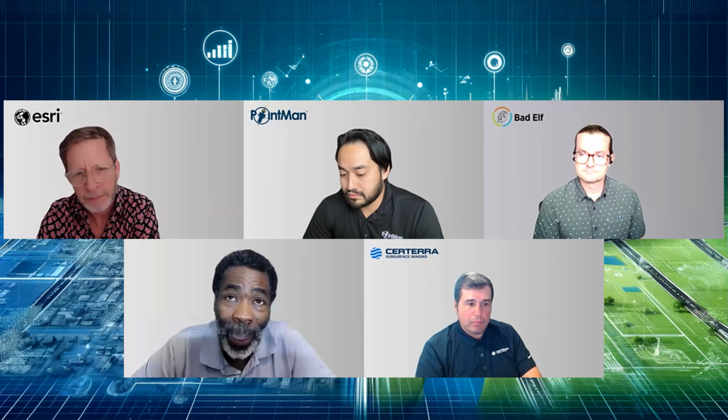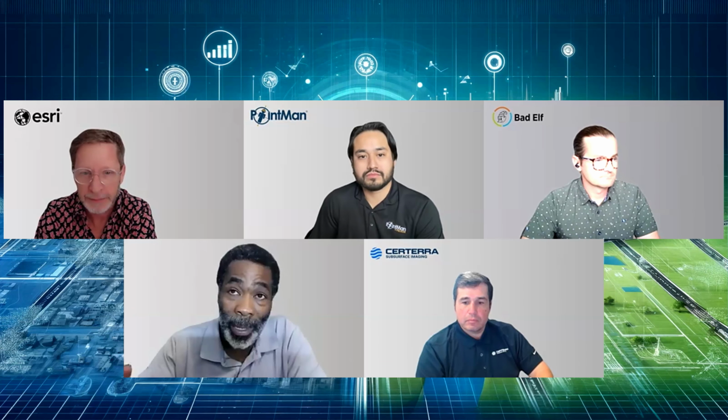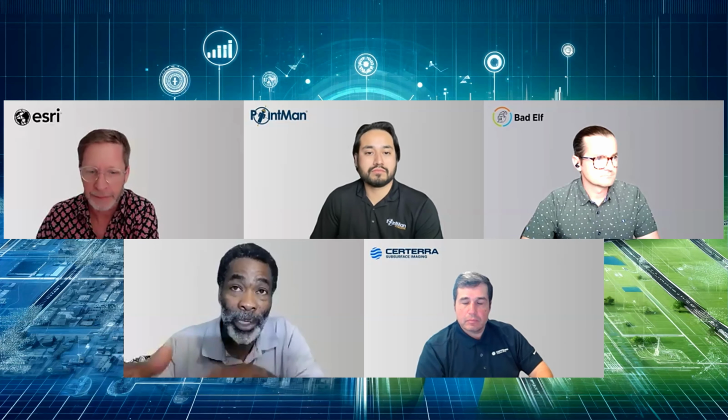Not to mention, I just want to shout out two companies. One is EnviroCal, and the other one is Reduct. They have a gyroscopic mapping tool that you can push through a pipe, and then they can give you the shape file, KML file, KMZ file. You can take that file, put it into Map 3D, and actually visualize the utility in 3 dimensions. Not only that, we had a project here in Fort Myers where we hired a company, I won't mention which, and they gave us the data, and we were able to stake out using PointMan the actual running line of the utility that we couldn't locate.